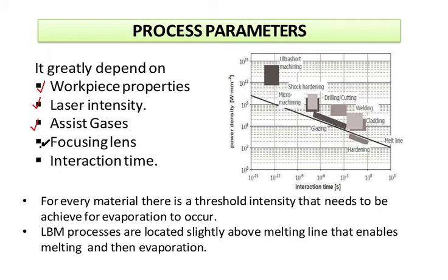Next important is your focusing length. You are going to maintain the focal length, and in that way you are going to achieve accuracy for drilling a hole or performing any operation. And that also depends upon you: what should be the focus length that you would like to go for. And last but not the least, it is the interaction time. Time is one of the most important factors.